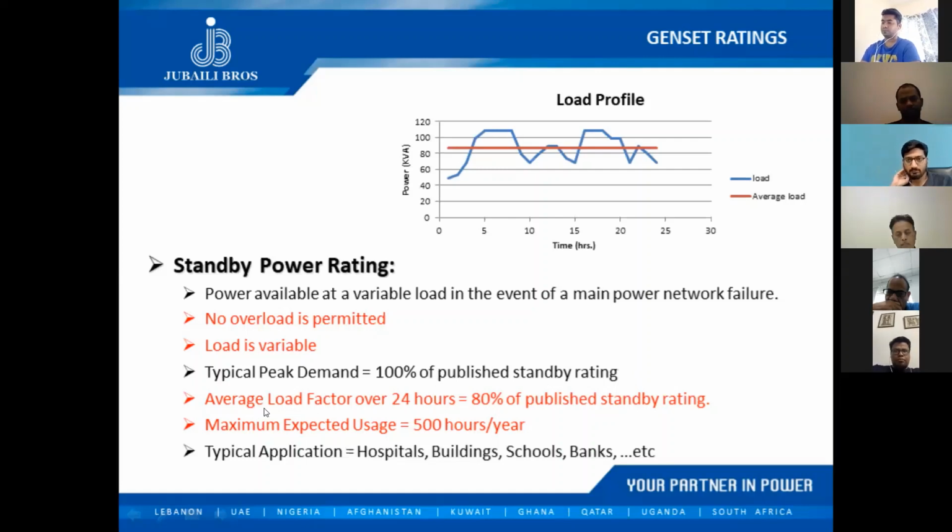Now, the average load factor over 24 hours is 80% of the published standby rating. So you see, guys, we're seeing some similarities here between standby and prime, but the rating differs. If we're talking about 100 kVA prime, 110 kVA standby, what's 80% of the published standby rating?